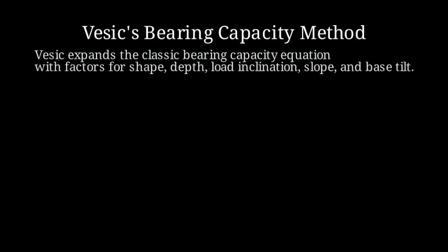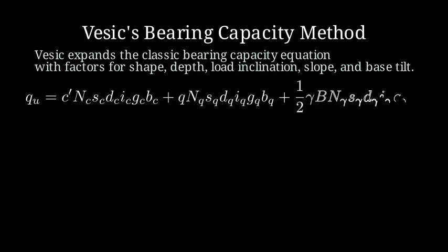Welcome to this lesson on Vesic's bearing capacity method. We will build intuition about the ultimate bearing capacity of a shallow foundation, showing how Vesic extends classic Terzaghi-style formulas with a rich set of correction factors. Here is the complete general bearing capacity equation using Vesic's approach. Each term represents cohesion, vertical stress, or unit weight contributions weighted by the full set of correction factors.